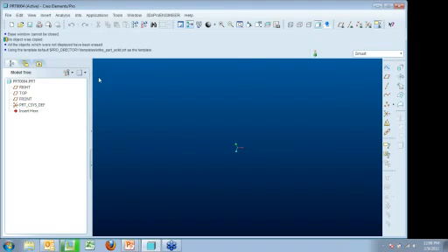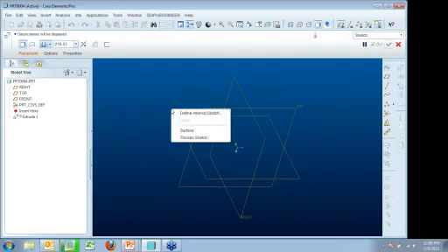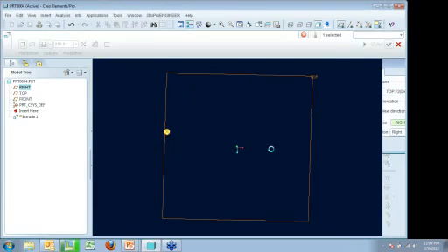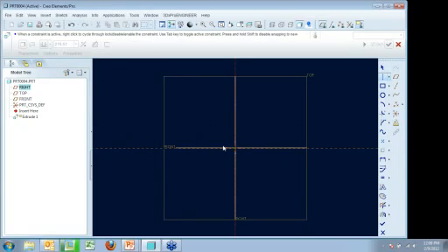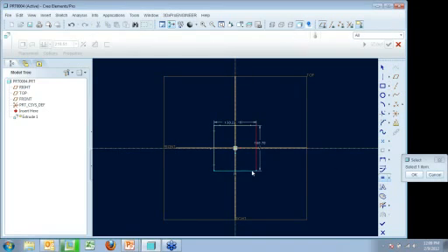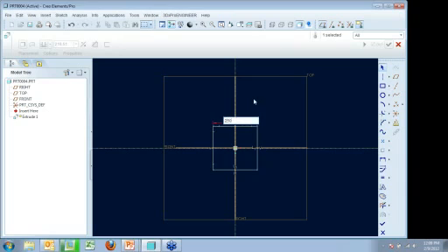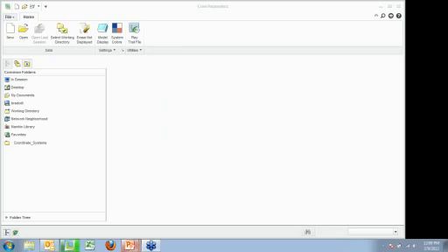So I'm going to show you. I'm going to sketch a real simple extrusion here, and you can see all of the different steps I'm going to take. It's going to be real simple: a square with another square on top of it. So I have to go in, create some construction center lines, make my square, then actually go in and set these two sides equal to each other. And we'll make this 250. All right.